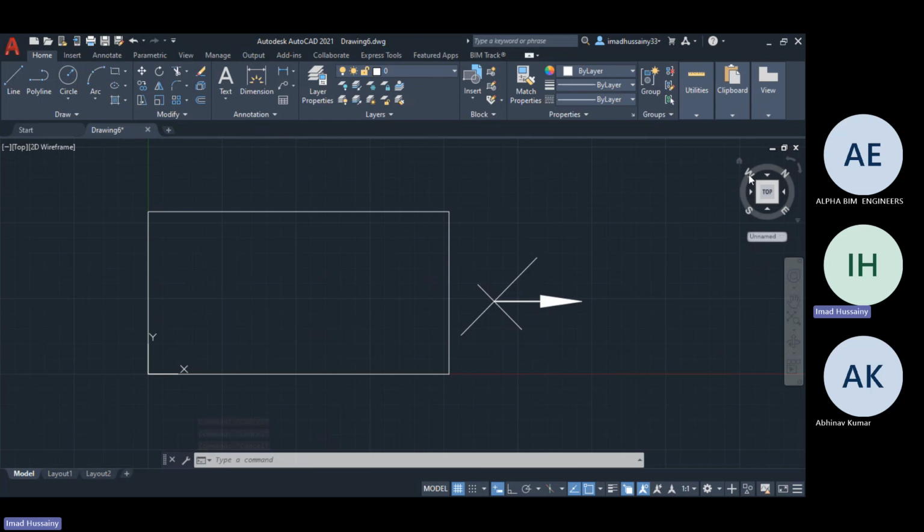Now my XY are straight, but you see our true north, that is our world coordinate true north, is showing like this. So this is my project north. I have matched my coordinate system to the project north. So this XY, the user coordinate system, you can change as per your requirement, wherever or however you want, in order to work properly. So this is your project north, but the true north is somewhere else. Tomorrow, if they ask you to match, just find the angle between both and rotate your drawing to make the adjustment.